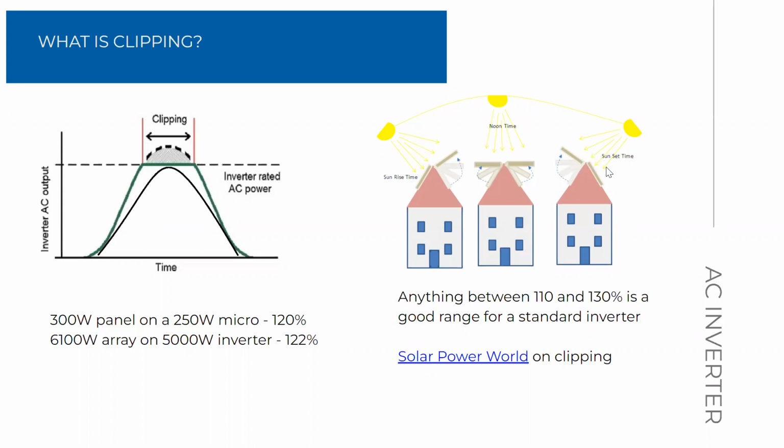And then similarly, if you have west-facing panels, the most sun exposure will be occurring with the evening sun. So most residential systems do not have a tracker. So the tilt of your panel is going to remain the same for 365 days a year. So as the sun changes in its height and the angle, as the sunrise and sunset time changes, the exposure of your array to the sun will change throughout the course of the year.